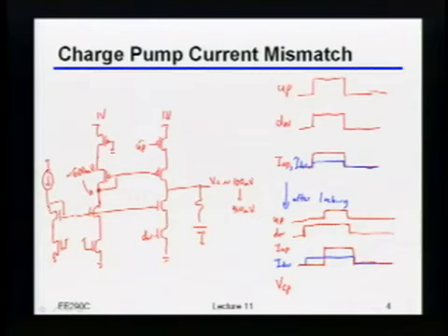So basically, every time you do this, the control voltage glitches down a little bit, and then, okay, my drawing's not great, but basically it glitches down and starts integrating down, and then glitches up, and then integrates for a while, and then eventually it reaches steady state, once the charges and everything have balanced out. So it's another little glitch, and long story short, it comes back to the same point. But I've created this weird glitch behavior. And oh, by the way, that glitch happens every single reference cycle, even if I don't have any noise at all, right?